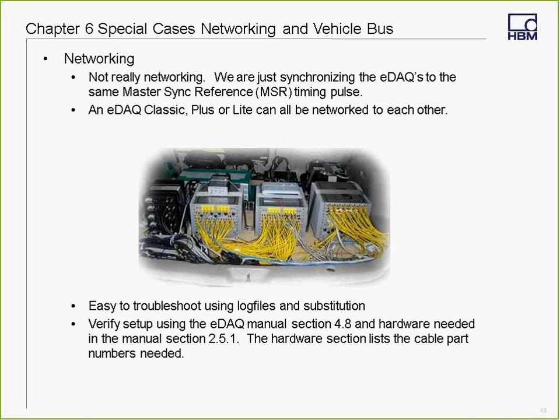Verify setup using the eDAQ manual section 4.8. It is a very good guide if you've never done networking before. If you follow that guide step by step, you should not have any problem to network your eDAQs. And the hardware needed is listed in the manual section 2.5.1. And the hardware section also lists the cable part numbers that are needed, and it also will break out how many of each of these cables you will need, for example, to network 3 eDAQs.